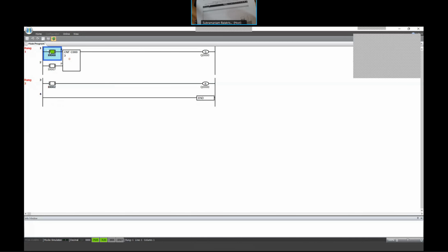Counter has got a value of 3. So this top line is the reset line. Right now it is on. I'm going to go and hit the trigger line. Has anything happened? Because this is locking it. So I'm going to reset this. I'm going to release the reset. That means it will allow the counter to do its job.